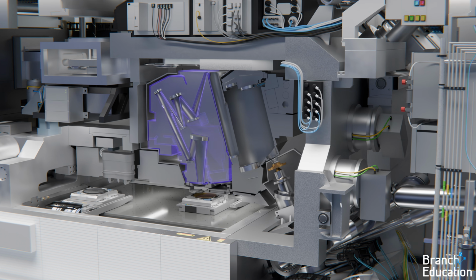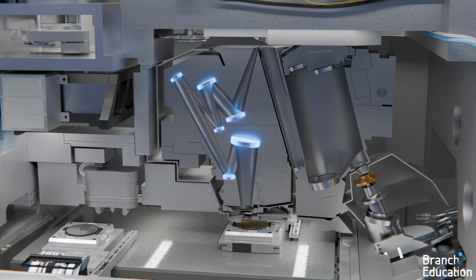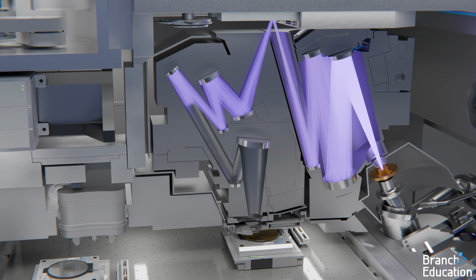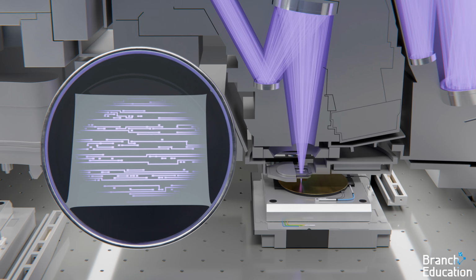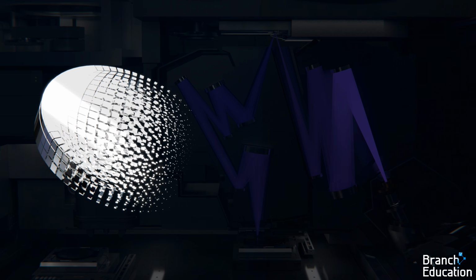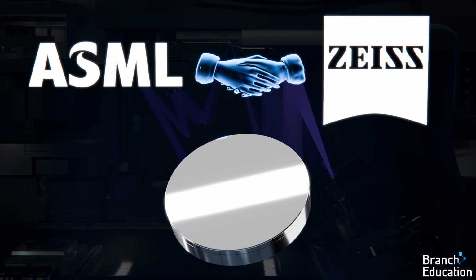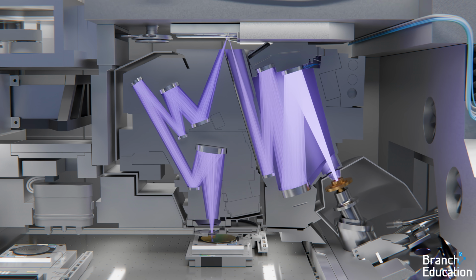So let's move on to the projection optics. These optics are composed of a series of mirrors that are used to project and focus the patterned EUV light onto the wafer with extremely high accuracy, while minimizing wavefront aberrations and shrinking the image by a factor of 4. These mirrors are designed and manufactured by Zeiss, who is a long-standing partner of ASML and has been a vital collaborator in the development of the optic systems inside photolithography tools.